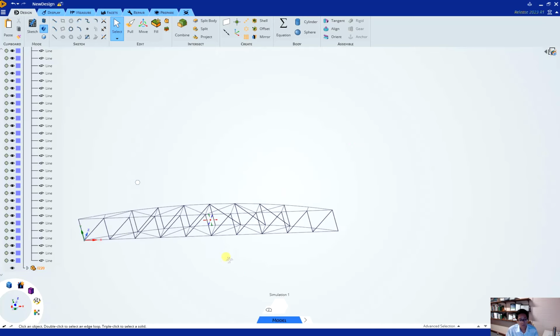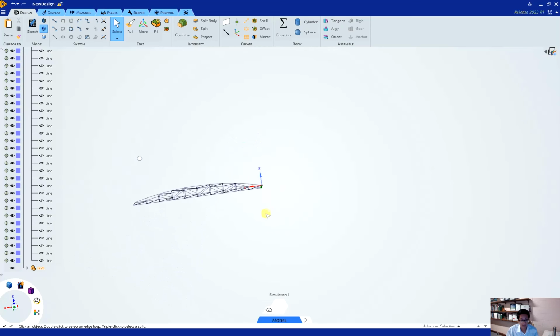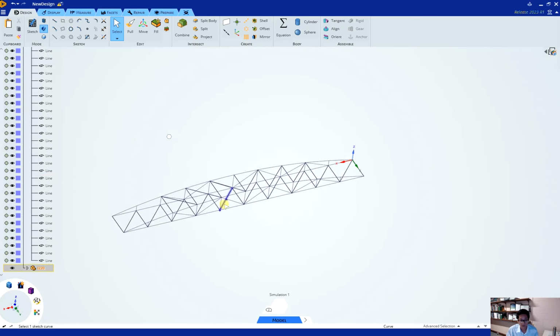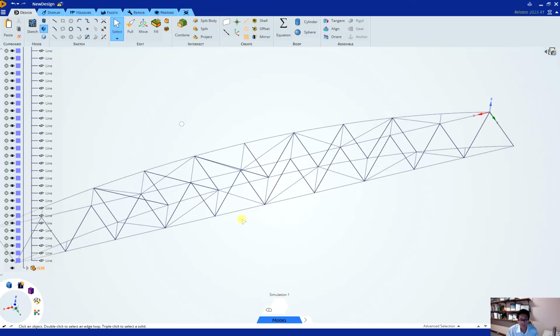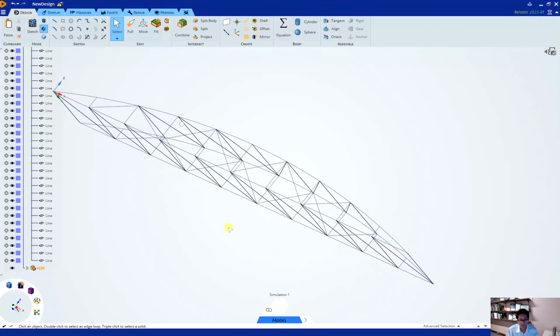Please remember two principles: that you must snap from end to end, and you shouldn't cross another element. Otherwise, they may not share the topology when they deform. The problem for enabling the 3D sketch is that you may snap to a point on another plane. So therefore, please very frequently check your bridge.